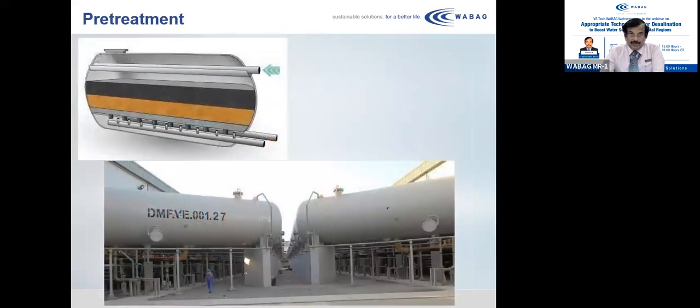This is a dual media filter. The arrangement shown here is in the 195 MLD Al Ghubra plant. We have 52 such big dual media filters. Dual media filters have anthracite and sand with a nozzle base at the bottom. So water flows into the top, is filtered through the anthracite and sand, comes to the bottom, gets collected in the nozzle arrangement through the header, and is taken into the plant area.